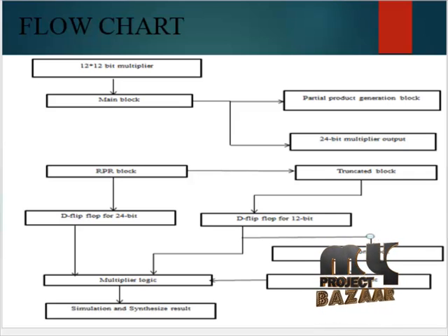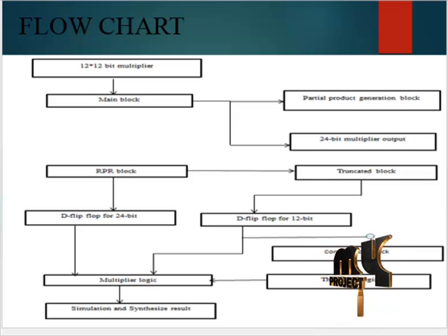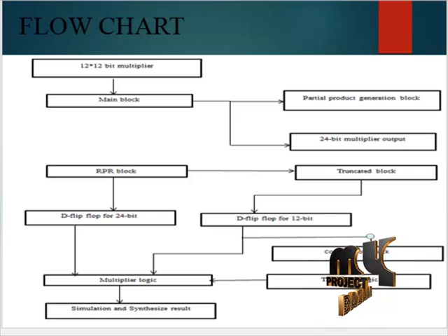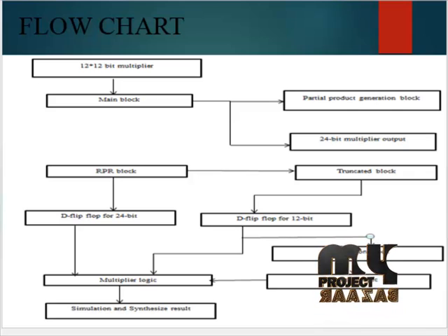In our process, we consider 60 approximate Radix-8 Booth multiplier designs, with approximate recoding adders, with and without truncation of the less significant bits of the partial product. These multipliers are faster and more power efficient than the accurate Booth multipliers. The multipliers with 16-bit truncation achieve the best overall performance among the approximate Booth designs.